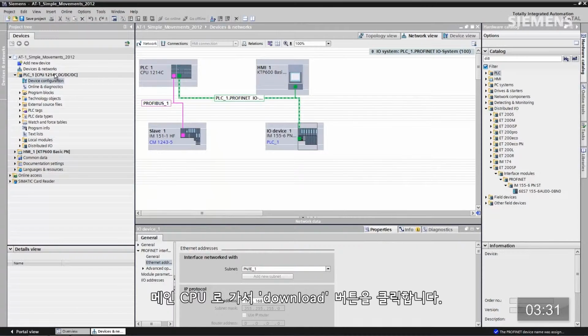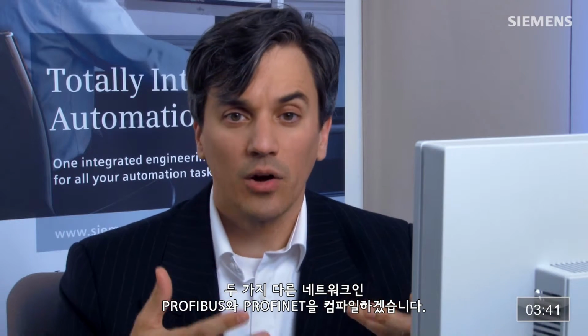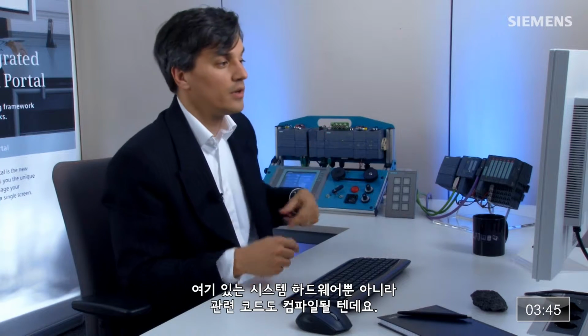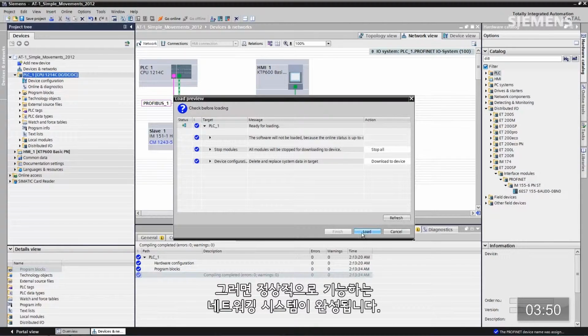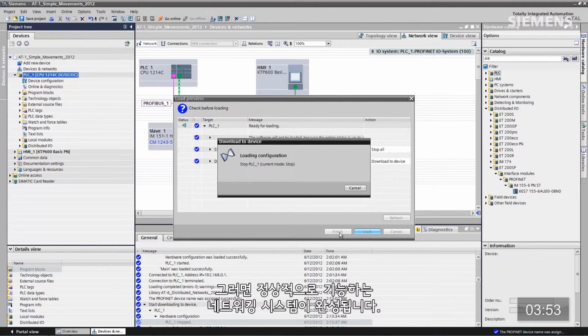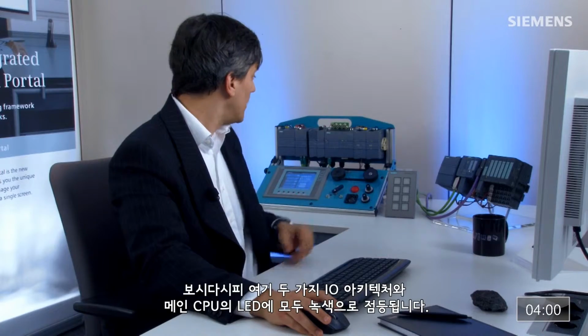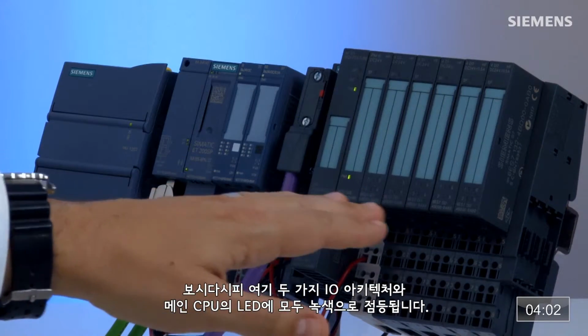Okay, so I can give focus to the main CPU and click the download button. Now we'll actually go back and compile the two different networks, Profibus and Profinet, including the associated hardware we put on it and all their attributes, along with all the current system hardware that we have, including the code. Once it's finished compiling all this, we can load it to the system, and we should have a fully functional networking system here. I click the load button, so now it's actually loading to the physical hardware itself. I click Finished, and as you can see, we have all green LEDs here on the two different I/O architectures and the main CPU as well.